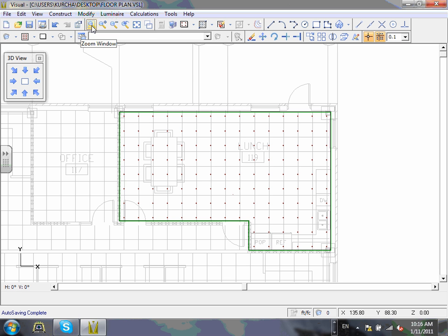You can, if you have, here's where you change. If you need to balance, like if I have 4 lamps, guys, I need 1 ballast for emergency light and 1 ballast for normal light. That's where you get 2 ballasts. You can use 1, 3, and 1. What do we have? We have 1, 3, and 1, 4. You can have 1, 3, and have another ballast for that 1 lamp. For the most part, you drive all the lamps by 1 ballast.